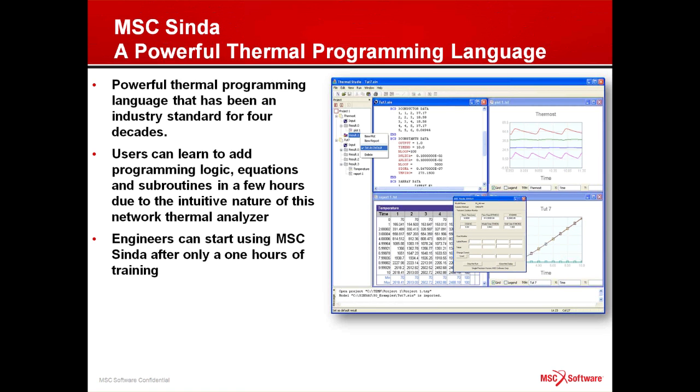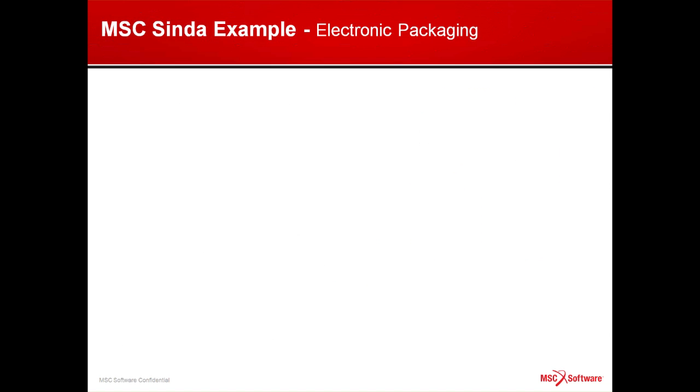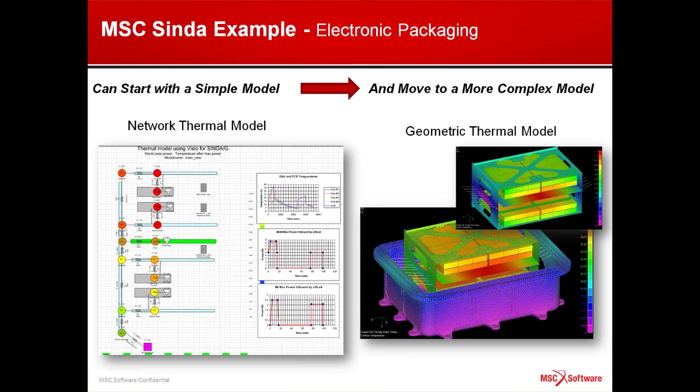You can start using Sinda after only about an hour of training, and it does have a nice Windows GUI, but it also transparently integrates into Patran for doing 3D geometric models using CAD, as we'll see in a few minutes. So let's look at an electronic package, and let's look at the simple approach, what we call our network thermal model, and then we'll look at a more detailed finite element model that's generated in Patran, but still using the same solver, Sinda, in both cases.